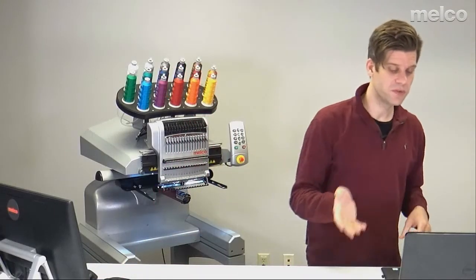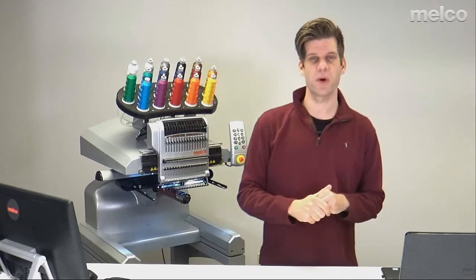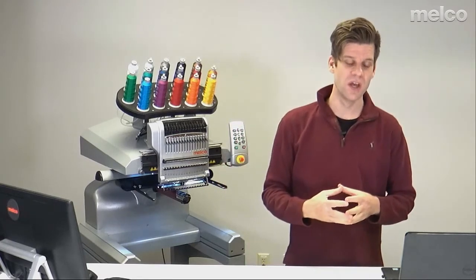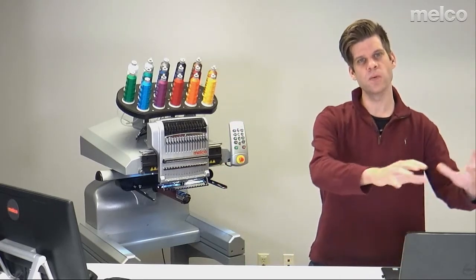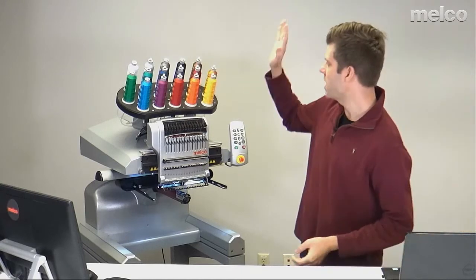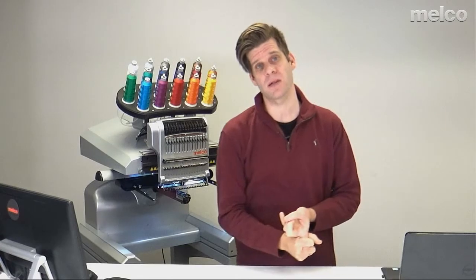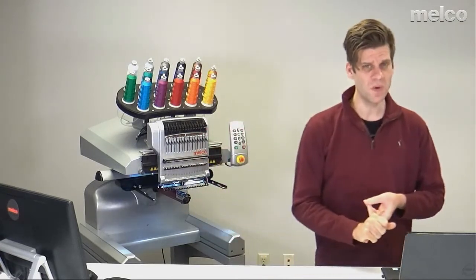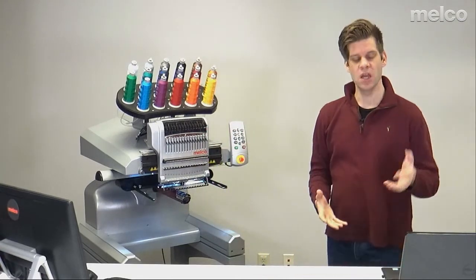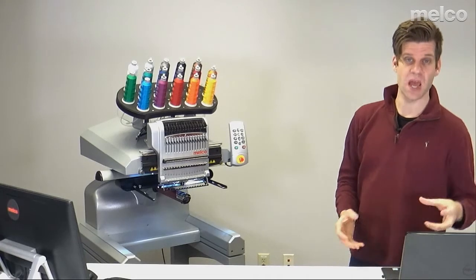When you go to set your color sequence in your software, it's really helpful to colorize the thread cone display that's in the software to match what's on your machine. That'll do a few things for you. One, it'll allow you to automatically set your color sequence. But two, even if you're not automatically doing it, you can look at your software, you can have it display